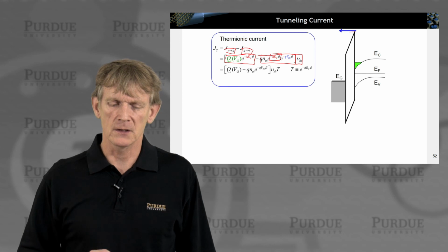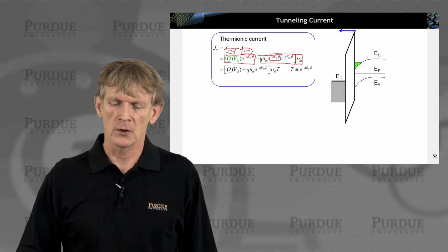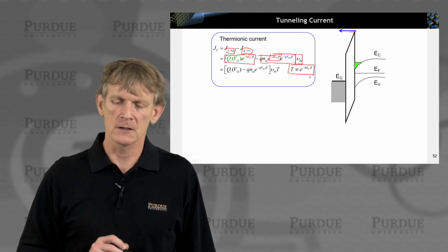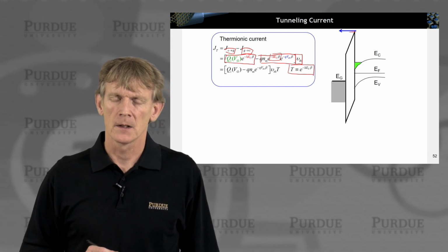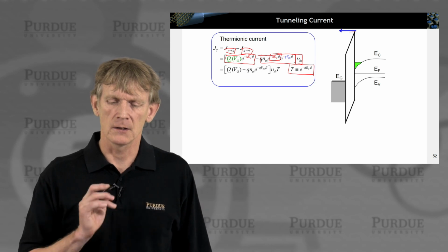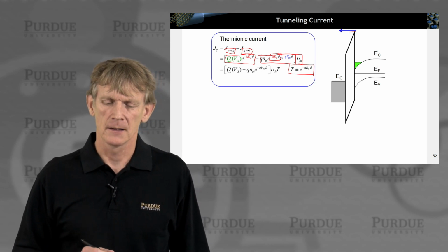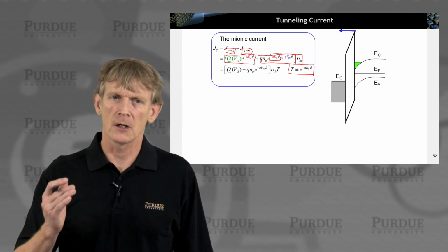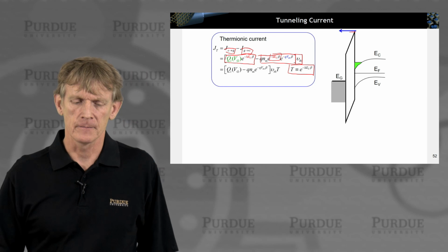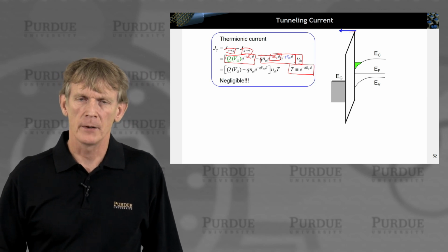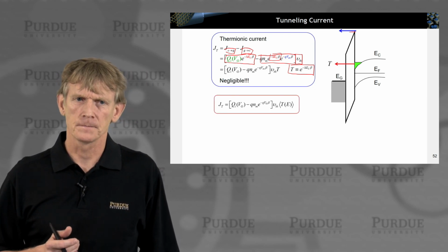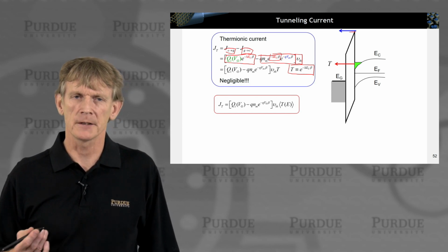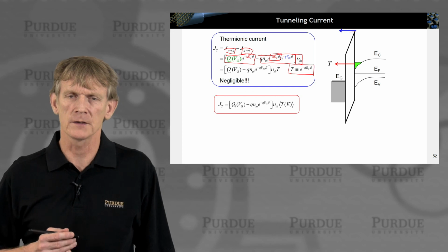So we can build out this difference between the two terms, and you can identify this with a tunneling coefficient, which is going to be minuscule if your barrier is big enough, because the barrier is so high. So that would be thermionic emission over the barrier, and that's negligible. But if you make this thin, then we've calculated tunneling through barriers in the early sections of this course.